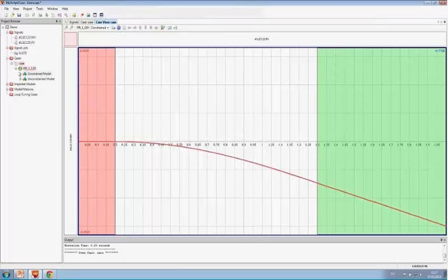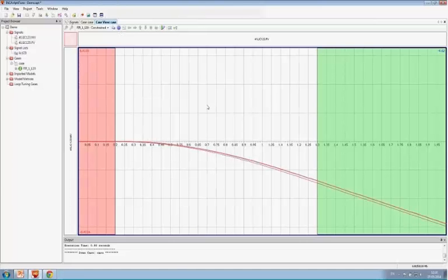So now it's turned red again, and I have to run it. After doing this, you see the model has changed slightly, and as a nice straight line from this moment, 1.3 minutes, and it had a dead time of 0.2 minutes.